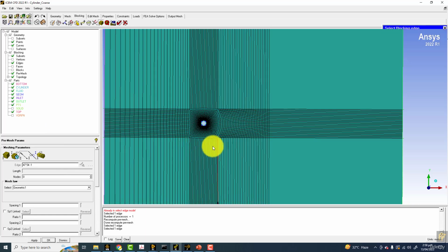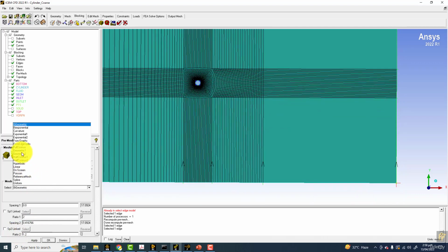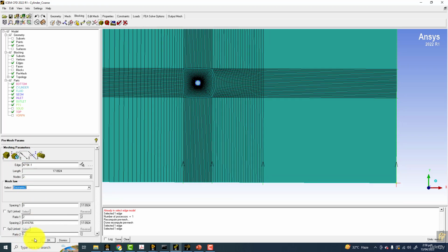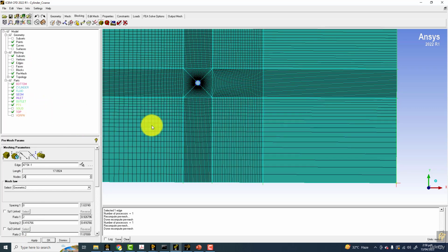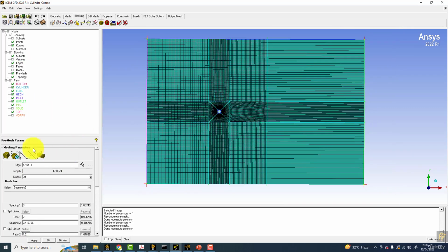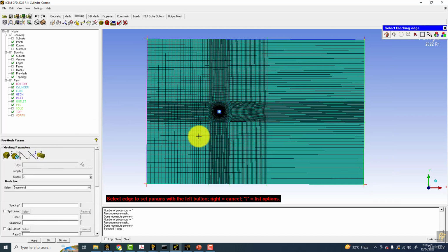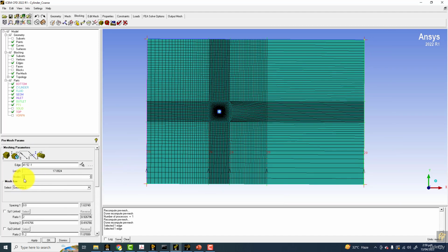Okay, you should be very much careful about the meshing here because the meshing is not very simple here and it requires a lot of considerations. So geometric 2 would be applicable here. Let me try. And 20 cells. Okay, so 20 cells were upstream. On the upper side, 30 cells are here, so 30 cells should be here as well.